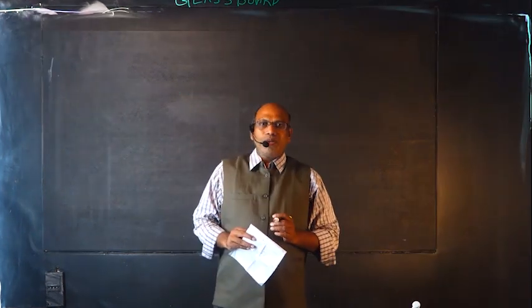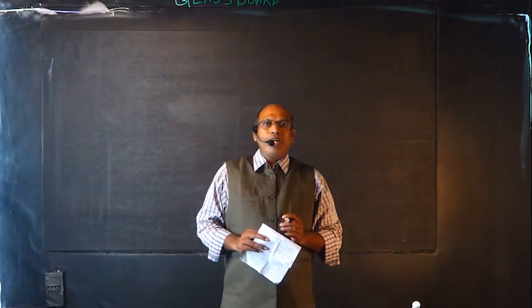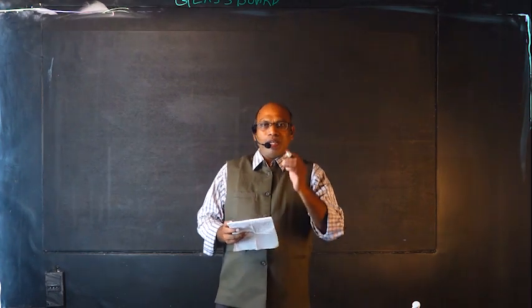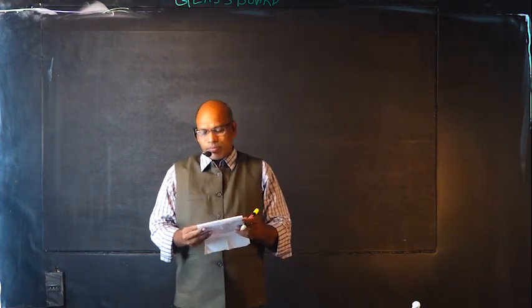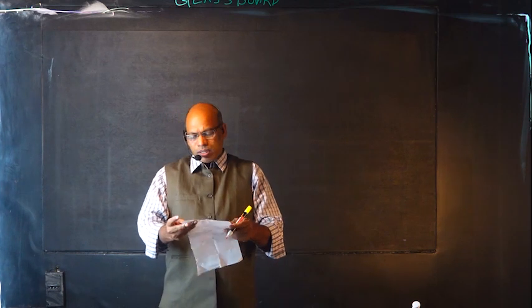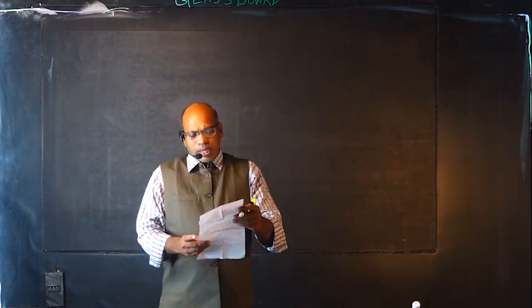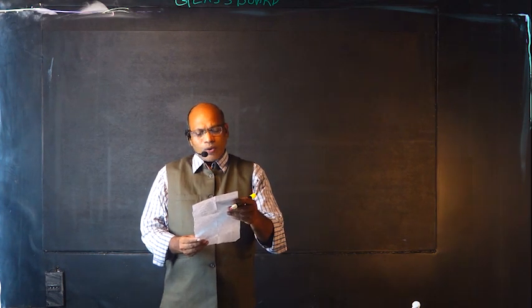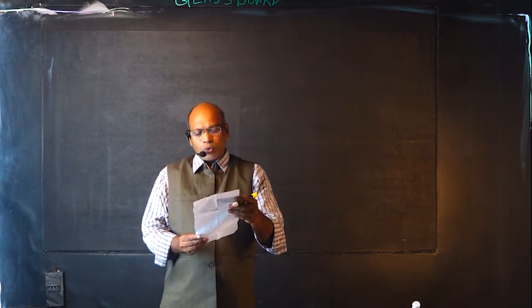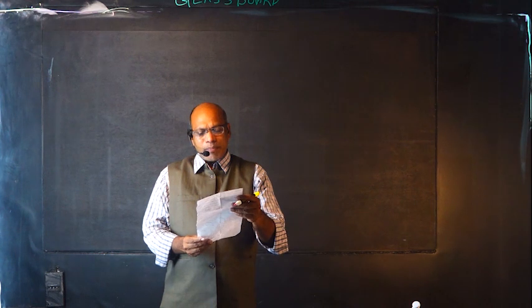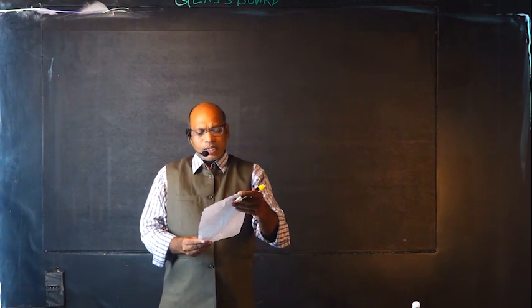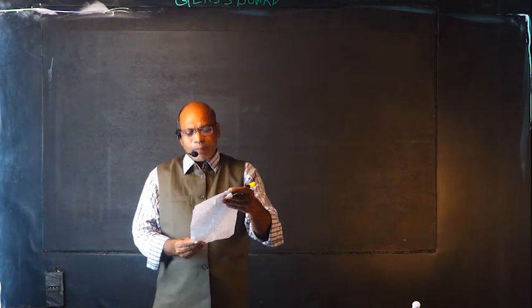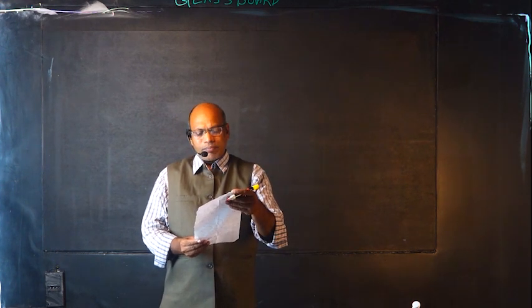Now we are going to discuss one more problem related to minor losses. Please note down the problem. At a sudden enlargement of a water main from 240 mm to 480 mm diameter, the hydraulic gradient rises by 10 mm.